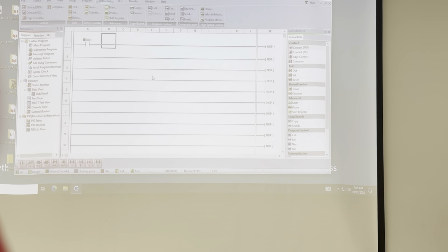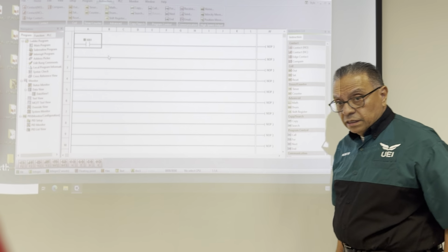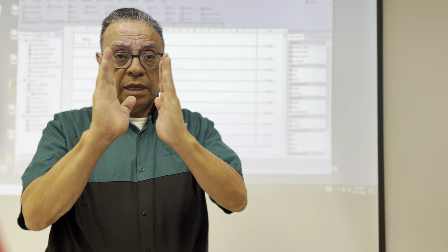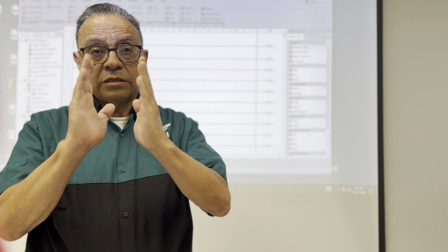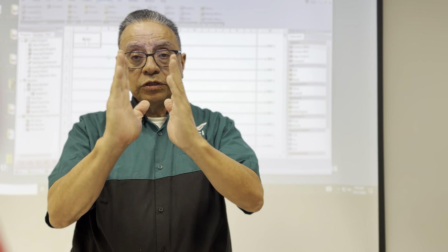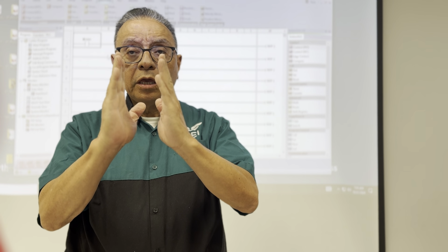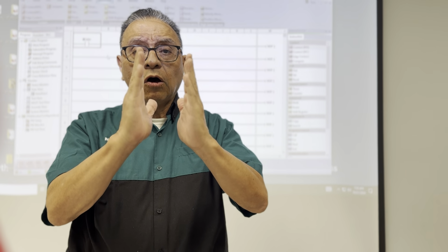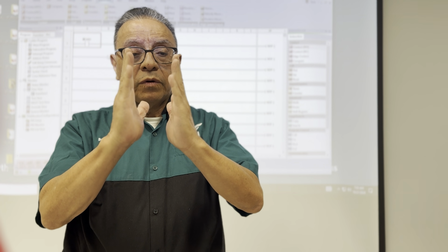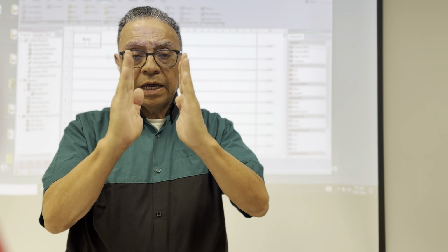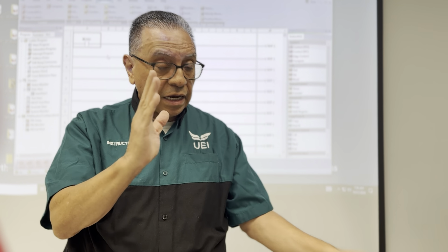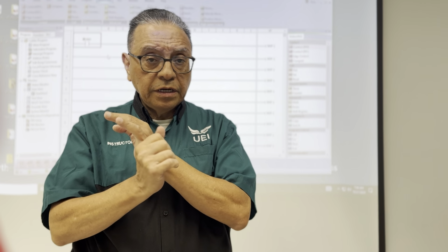In the traditional ladder diagram, this represents a normally open contact. It could also represent a switch, okay? When it's open, it's false. When it's closed, it's true. Now we have a normally open contact that could be capturing, at the hardware level, the input of any switch.